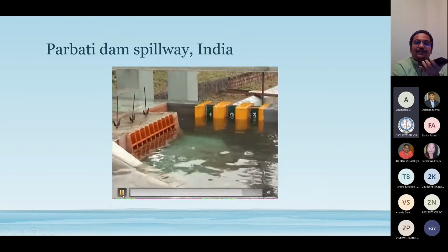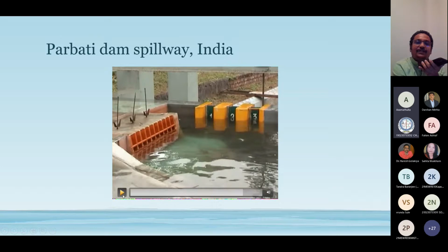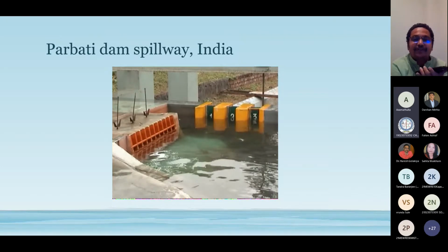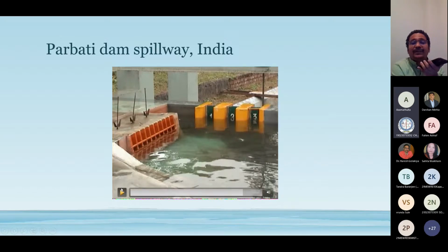Thank you so much. You can see here the strong vortex will take place at full reservoir level. I still believe the elevation is 198. So such a thing, and also gated operation. Whenever there is gated operation, the jet is thrown very high downstream. So there is some benefit, but we also have to have scour downstream. That one, no doubt about that.